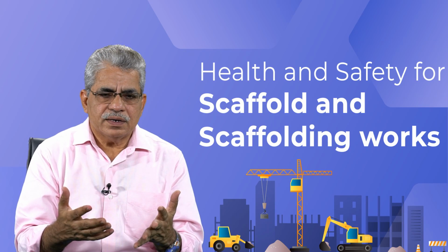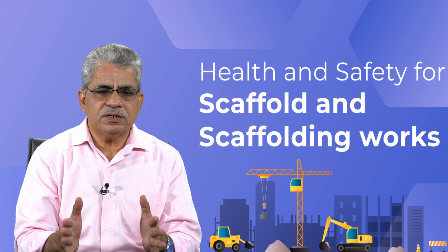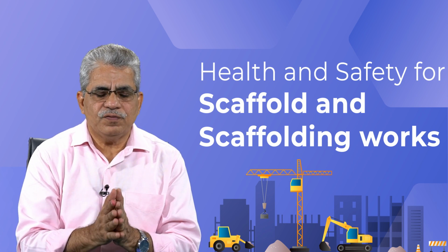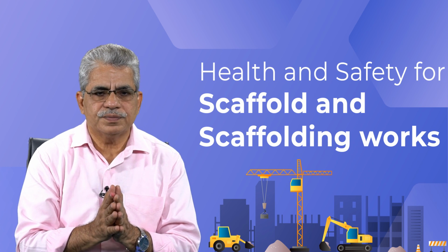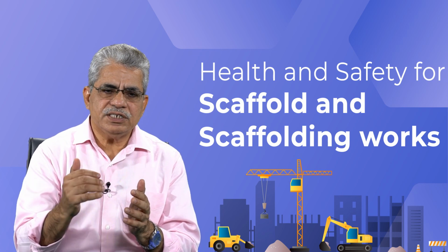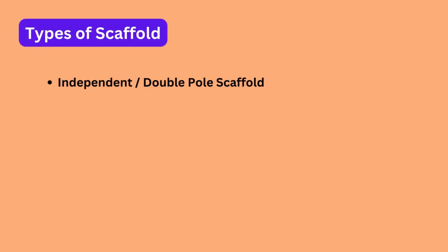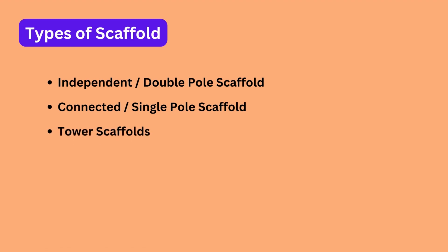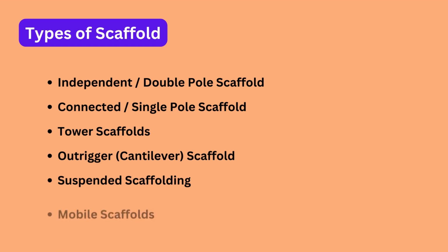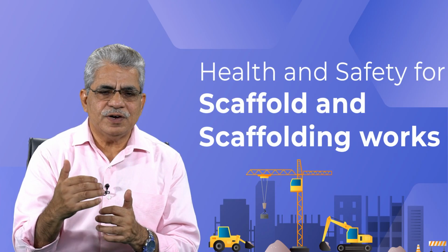Now, after introducing you to the different components of the scaffold, let us know about the types of scaffold or classification of scaffold. Scaffolds may be classified into different categories such as independent or double pole scaffold. Second is connected or single pole scaffold. Then tower scaffolds. Then cantilever or outrigger scaffold. Then suspended scaffold. Then mobile scaffolds. Let us understand these one by one.